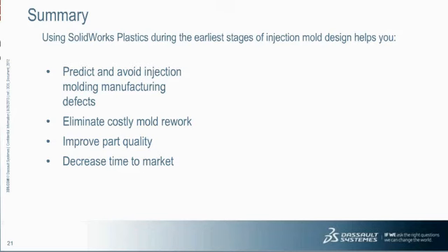So TPEs, thermoplastic elastomers, are actually composed of both crystalline and amorphous regions, but I think you would generally characterize those as crystalline materials. And of course, as a thermoplastic, they can be heated, melted, formed, cooled down, reheated, formed, cooled down, and so on. That's one of the inherent characteristics of thermoplastics.